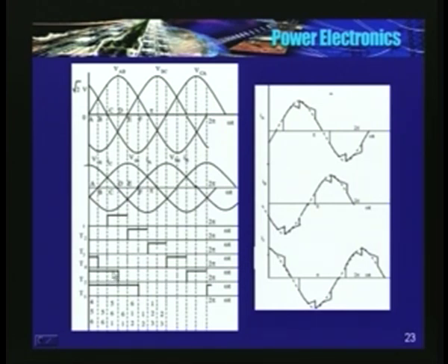So remember, if three thyristors are conducting, I need to use IA plus IB plus IC is equal to 0. Load is resistive. So till the phase voltage becomes 0, the equivalent circuit which consists of three thyristors is valid. The moment one of the phase voltages becomes 0, the thyristor which is connected to that phase turns off, and till the new thyristor is triggered, only two of them will be carrying current.